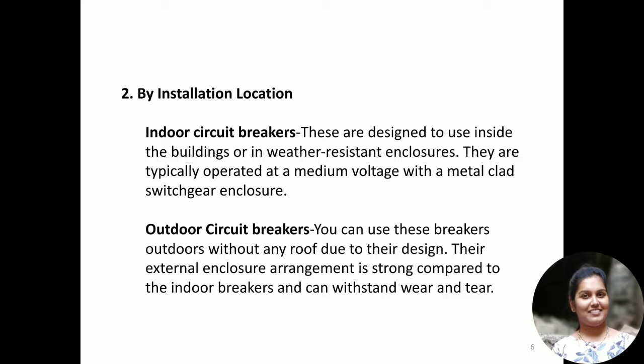So generally these kinds of circuit breakers operate at medium voltage with a metal clad switchgear enclosure. So the rating will be of medium voltage rating and will have a metal clad switchgear enclosure.